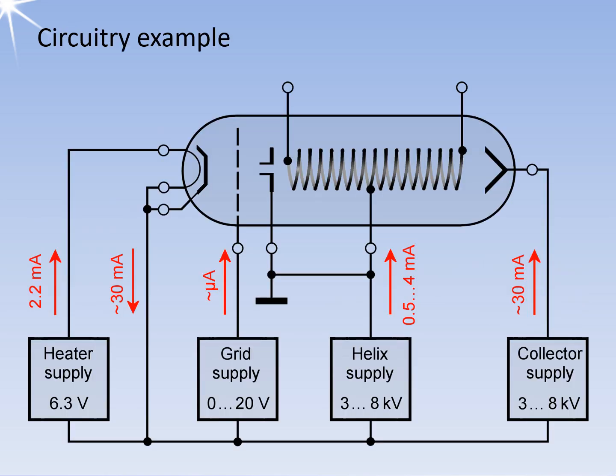The slide shows the power supply arrangements for a typical helical TWT. The beam current is controlled by the grid-cathode voltage. This grid can also be used to block the tube with a negative bias and thus realize a pulse mode completely. The blocking voltage is then superimposed with a positive square wave pulse. The circuit that drives the control grid is usually referred to as a grid modulator.